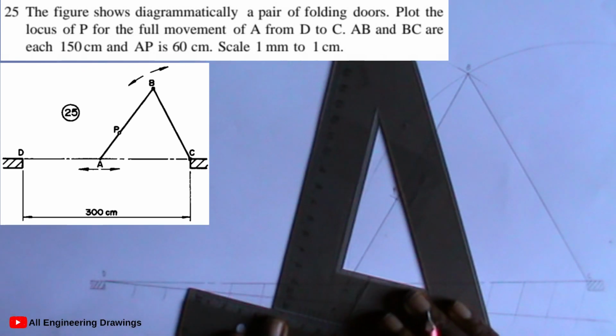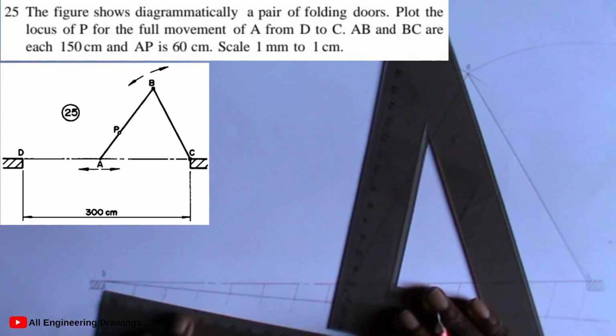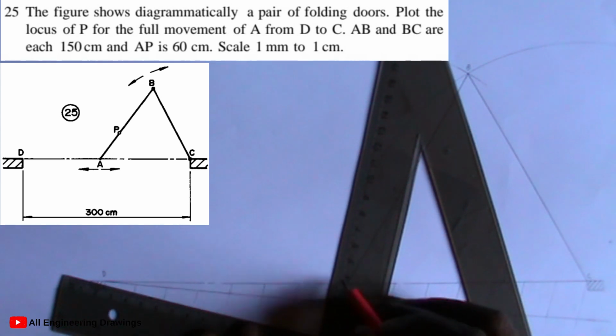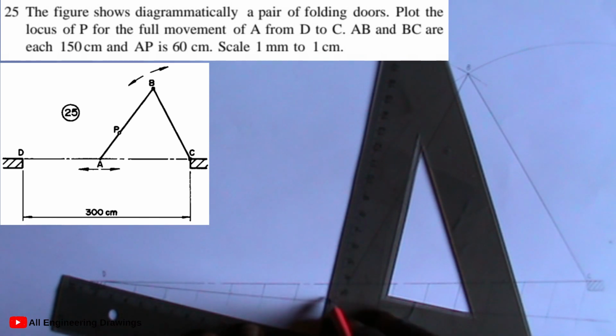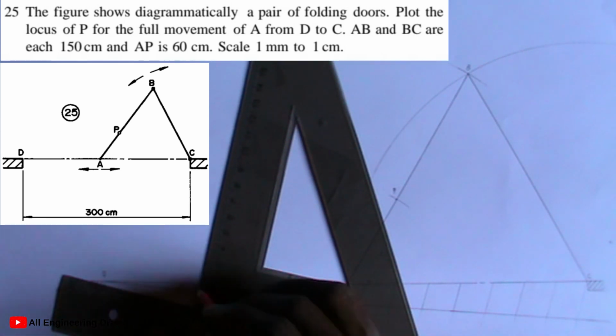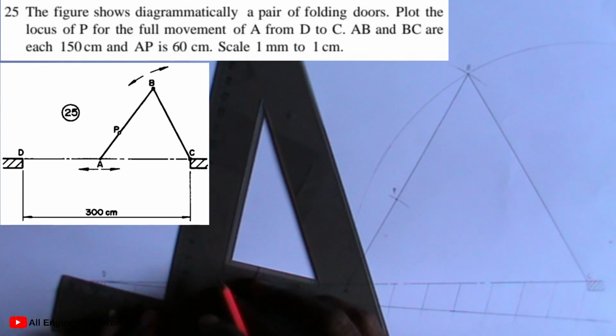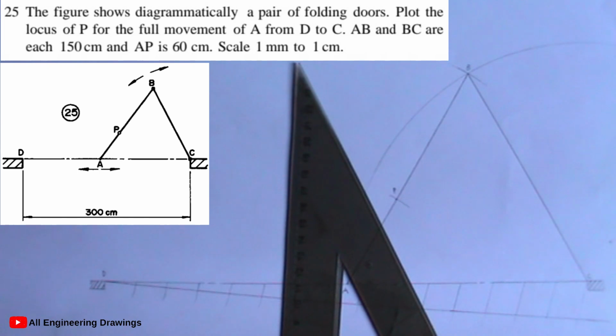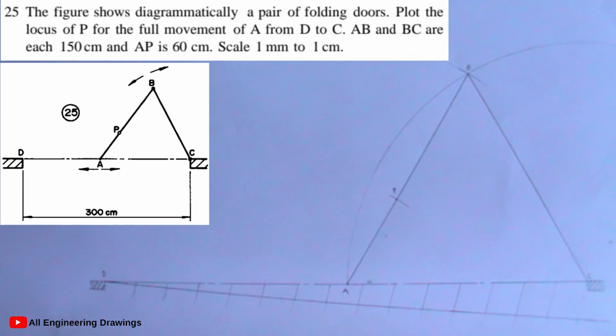So you can readjust with previous points. You ensure that this side of the set square is parallel with the previous lines you draw. Then finally, the last point. So after drawing your line, that is after dividing your line DC into equal parts.